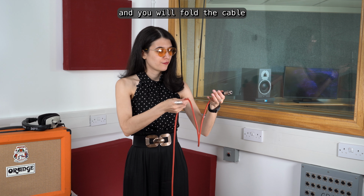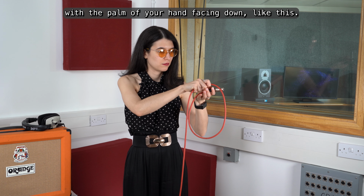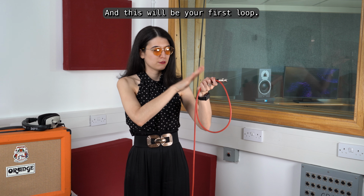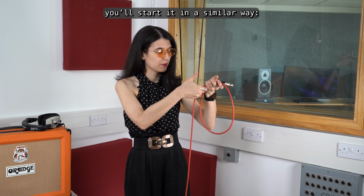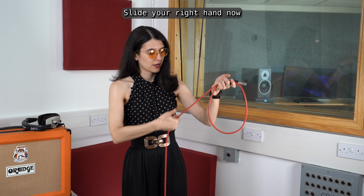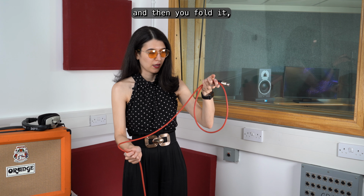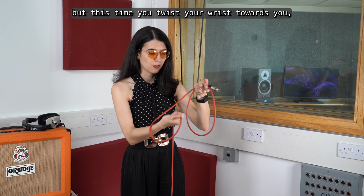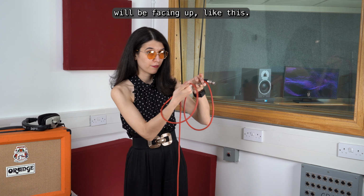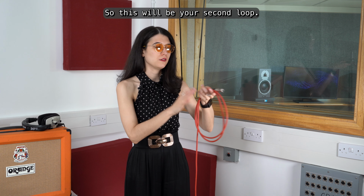and you fold the cable with the palm of your hand facing down like this, and this will be your first loop. For the second loop, you start in a similar way. Slide your right hand down until you've got a reasonable length of cable, and then you fold it, but this time you twist your wrist towards you and the palm of your hand will be facing up like this. So this will be your second loop.